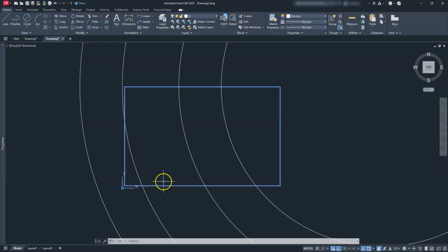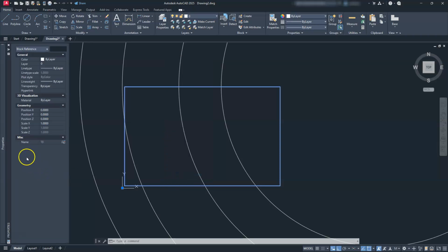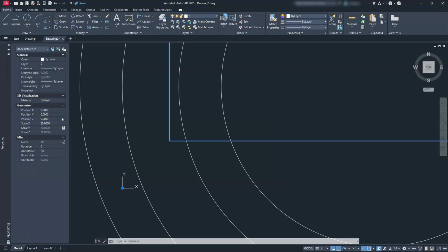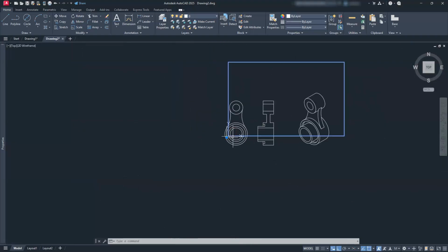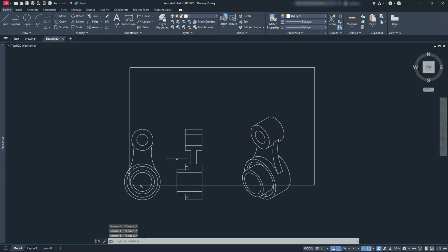So with this highlighted, I'm going to right click and select properties. Should open a dialog box. I'm just going to tell it my scale X, in this case, is going to be set to 20. Now, you can see how my scale Y and scale Z are grayed out, and that's because I had the scale uniformly checked in the box when I created it. But if yours aren't, you can just type in 20 in all of the rest of these boxes and everything is going to work fine. Okay, so I'm going to leave all of this stuff at full scale.